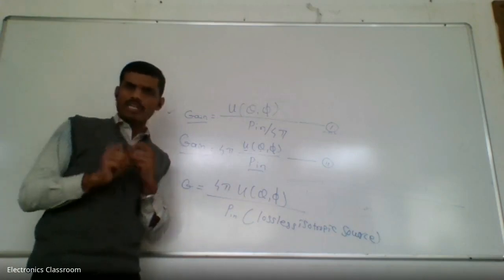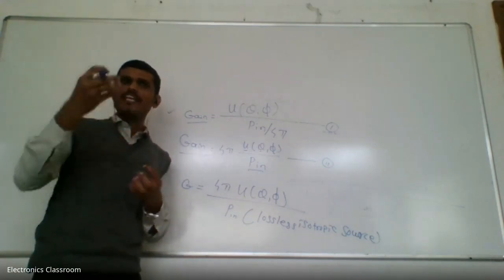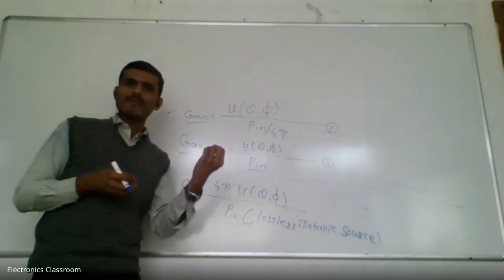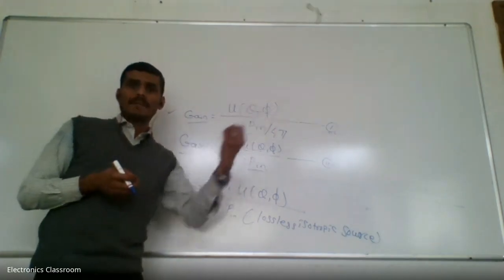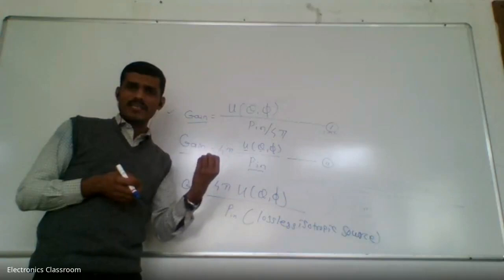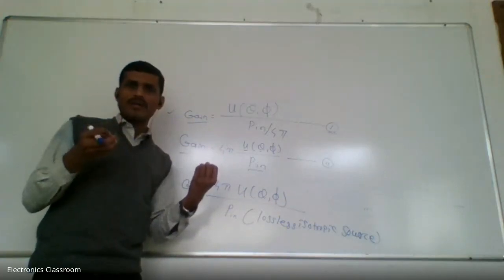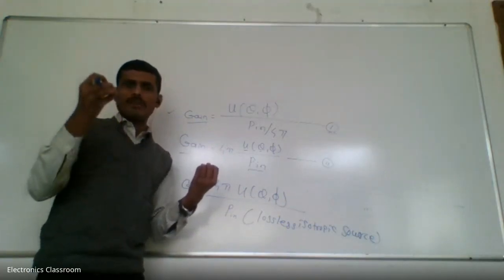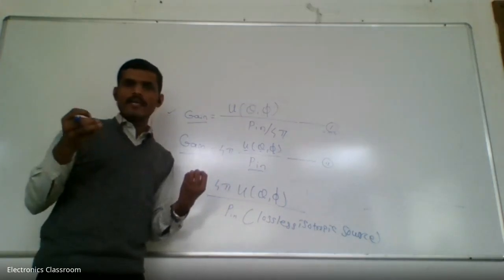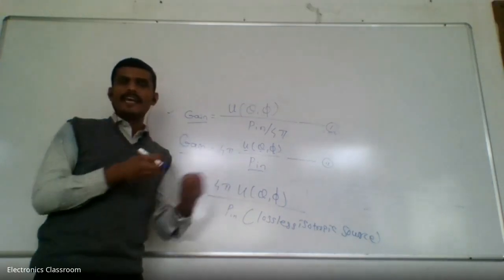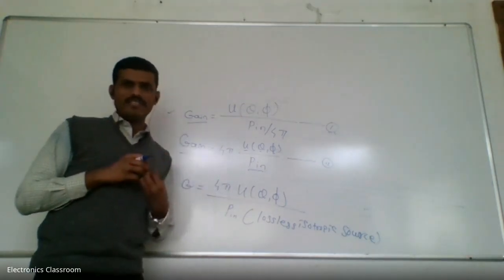Now by using antenna efficiency, again we can rewrite the total radiated power. Total radiated power means input power times efficiency. Now, the input power is equal to P_rad divided by your dielectric and conduction efficiency.